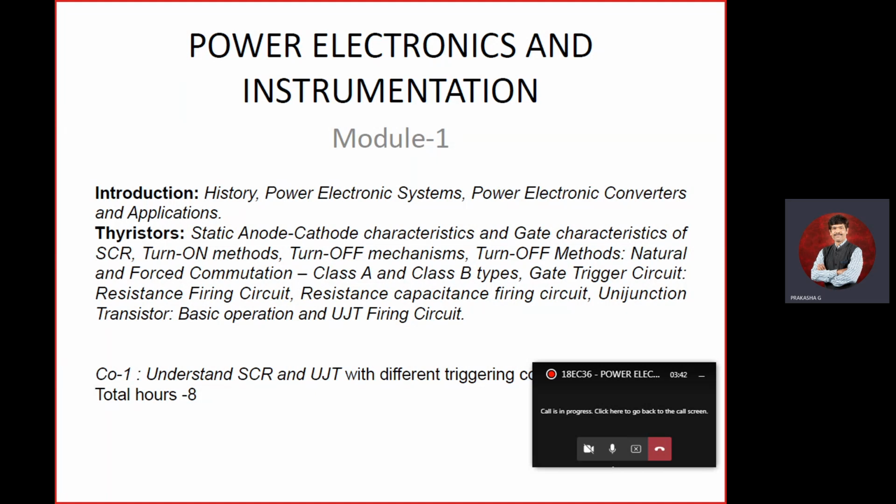After some time, that is your germanium and silicon. Germanium diode and silicon semiconductor devices will be there. Both of them will be at different points, like 0.7, 0.3. You might have heard about that. Based on that, the characteristics keep on changing. If you are using a germanium diode, it is going to be different. If you are going for silicon, you are going to get different characteristics. A slight change will be there. Those things I have already shown in LTspice projects also.